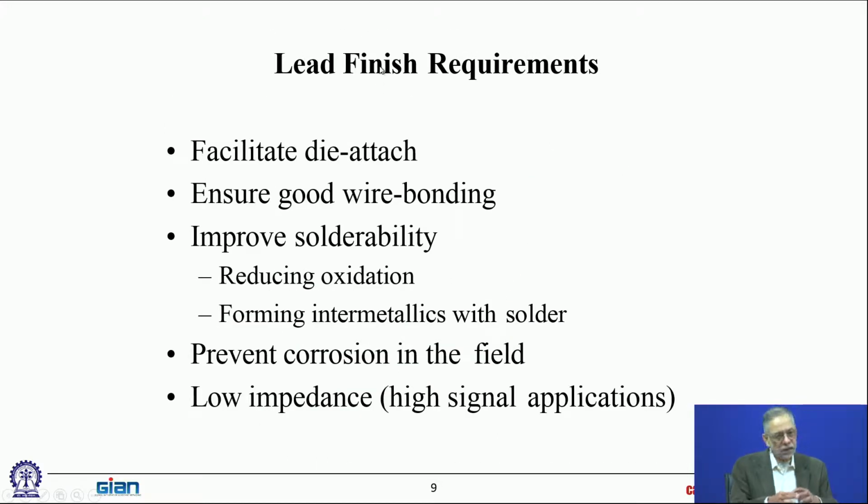So that's the solder, and then you need finish material on the plating, both on the printed wiring board side, the pads on the printed wiring board, and the finish on the lead or the pad on the component side. Those finishes basically promote a bunch of stuff. That finish allows good die attach, good wire bond at level 1, but at level 2 it improves solderability, because otherwise the pads are basically copper, the leads are basically copper, and they're going to oxidize. Just in storage they're going to oxidize.